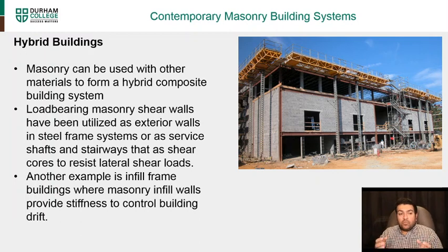Another example is infill frames in buildings, where masonry infill walls provide stiffness to control building drift. If you just have steel beams sticking out of the ground, the whole building will be moving, right? But if you put this wall system inside the steel frame, it stiffens the structure, so it does not move as much. Masonry walls are used a lot in areas where there is a lot of earthquake activity because they work really well in transferring the lateral loads that impact the building due to earthquakes.